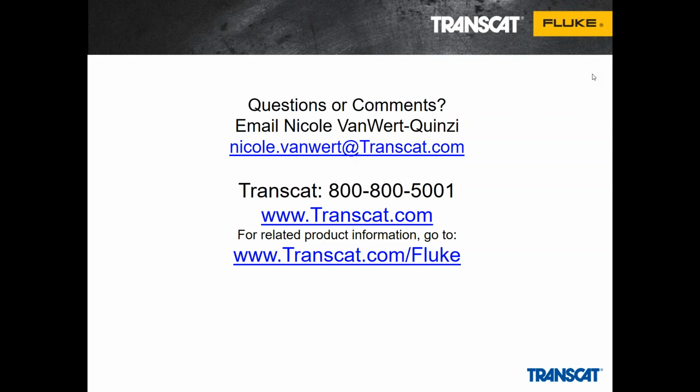Okay. Does the HART functionality in the 729 or the 754 replace the need for a HART communicator? That's a good question. We get that a lot. The 754 does not have the full functionality of the Emerson 475 or the Trex unit. The philosophy and design of the product is intended to not require a communicator for routine calibration and maintenance, essentially covering the trimming functions and the routine maintenance functions that a field calibrator would be required to perform, but it is not a direct replacement for the Emerson communicator.